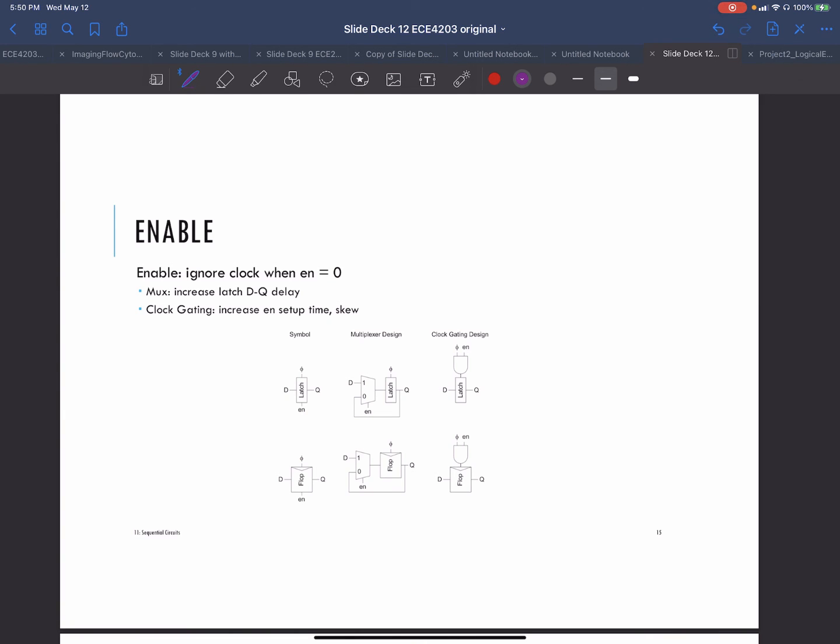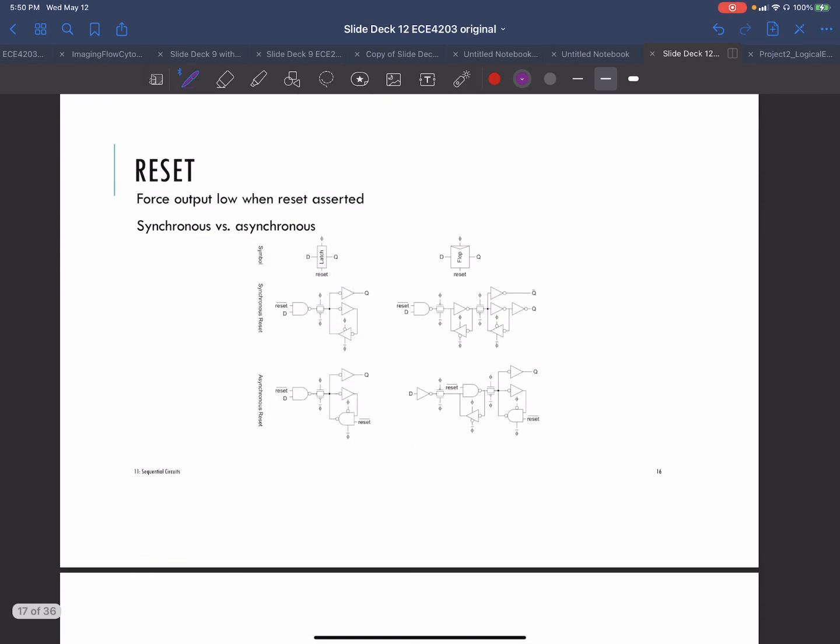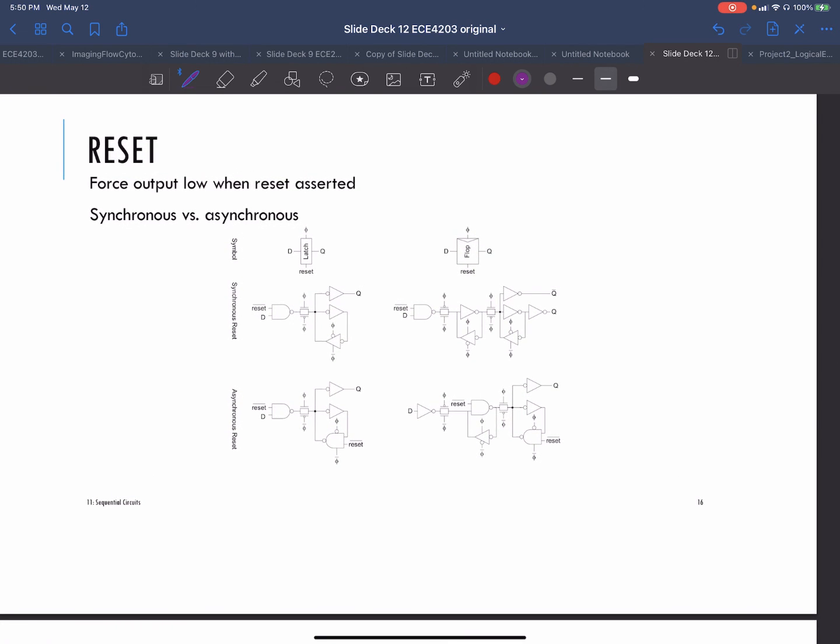And then you can go through a lot of variations in flip-flops. Enables are very important in flip-flops. You don't want them to always work. And resets are absolutely important to flip-flops. If you don't ever remember anything about this class except for this, it might save your life someday: make sure that you can reset all your latches.